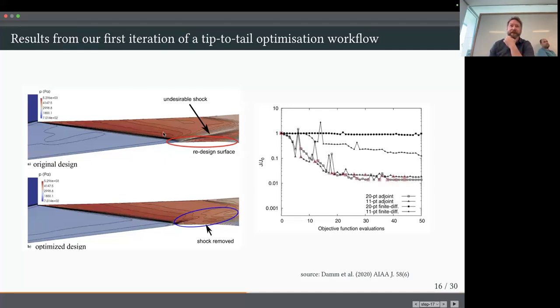So here is a simulation of the original experiment, but the experiment results also bear this out, and you can compare on a pressure rake across the inlet to confirm that. So here was the unexpected result. There was this undesirable shock that wasn't planned on, and it was essentially an effect of the viscous correction not being correct.